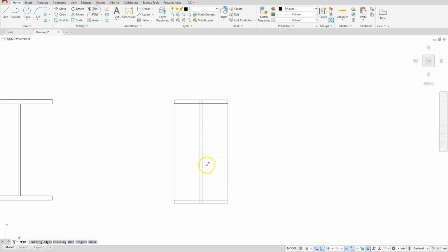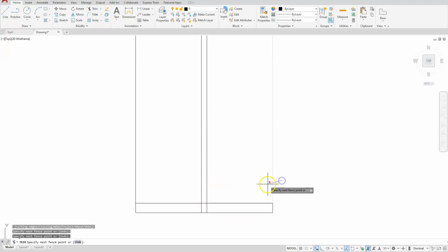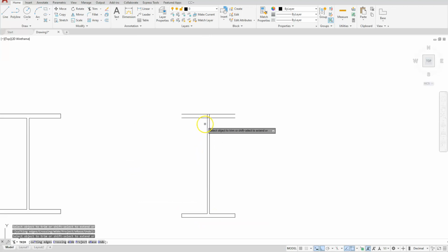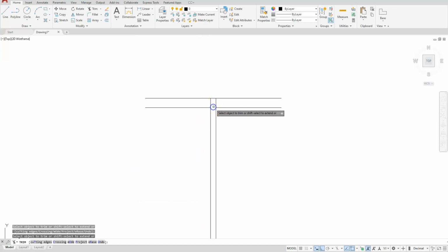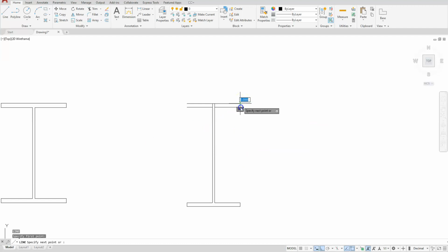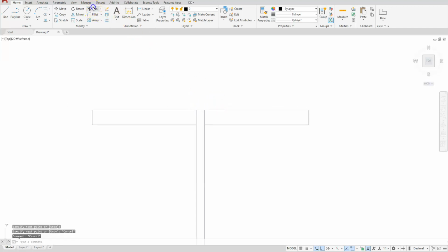Trim, and then we can trim off the lines on the outside and clean up on the inside. And that's strange, I think because I had my window zoomed in a little too close, it cut off my top endpoints. I'll go ahead and put them back. Then I'll come back to the trim command and cut off these lines.